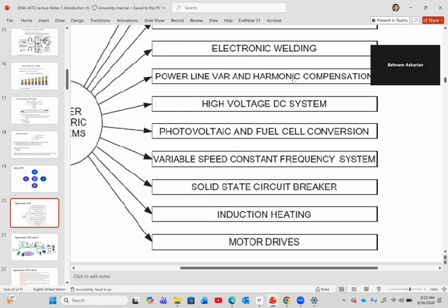This is exactly what happens in these inverter HVAC systems, and fridges and freezers. From 10 years ago, you can see everything has an inverter, like an inverter HVAC or inverter fridge. So the good thing about these motors is, previously in a refrigerator, the ones that don't have an inverter, or an HVAC, the compressor would turn on for like 20 minutes and then shut off, and then turn on and then shut off. And that creates a lot of waste in the system and heat, and it degrades the components of the system, the compressor.